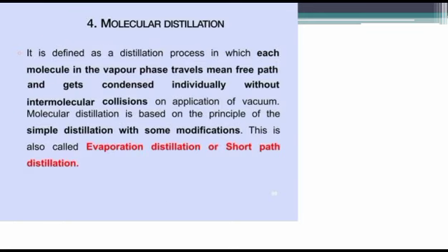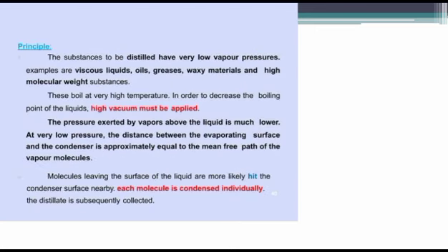Molecular distillation is defined as the distillation process in which the molecules in the vapor phase transfer within the mean free path and get condensed individually without intermolecular collision. On application of vacuum, molecular distillation is based on the principle of simple distillation with some modification. This is also called evaporative distillation or short path distillation.